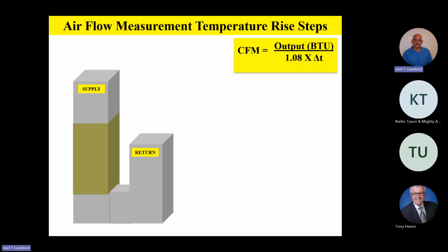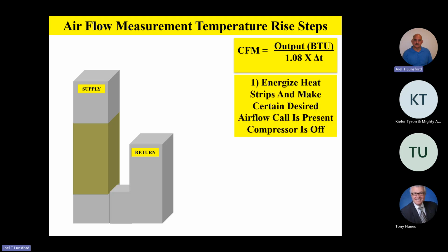So the temperature rise method. CFM is equal to the output of the device in BTUs divided by 1.08 times the temperature difference of supply and return air. So let's plug in some numbers.